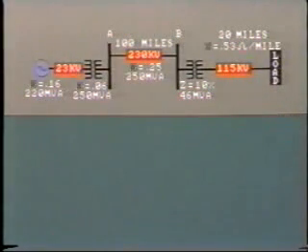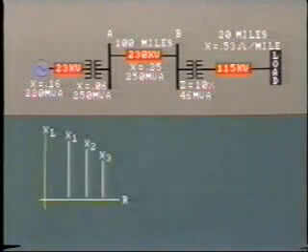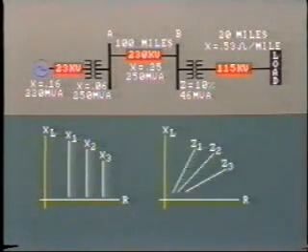Incidentally, the drawings will more often indicate the per unit values for X, that is, reactance, instead of Z, impedance. This is because, from the point of view of fault calculations, most of the impedance is made up of reactance. Also, it is more correct to arithmetically add reactances than impedances, which may be at different phase angles. Either way, the difference is not significant. Hence, the use of X values is quite acceptable and satisfactory.